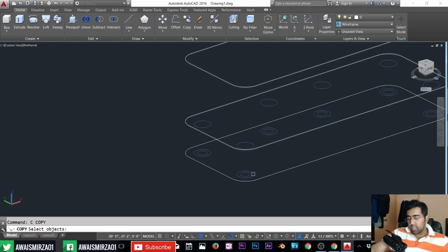So I'm going to select P. That's a shortcut key for what you just selected before. If you type P and then press spacebar, it will automatically select the last selection. Very useful. Press spacebar to select that. Now I'm going to type 0, 0, 1 feet and then 5.5. That should be fine now.